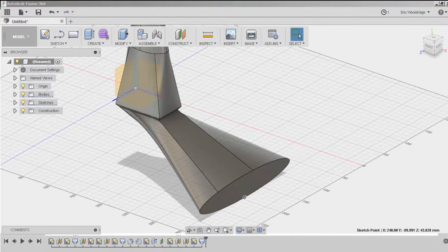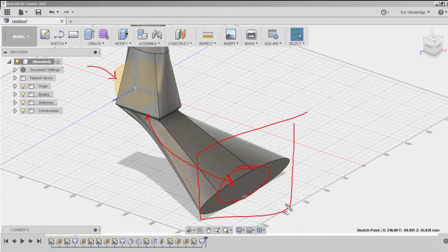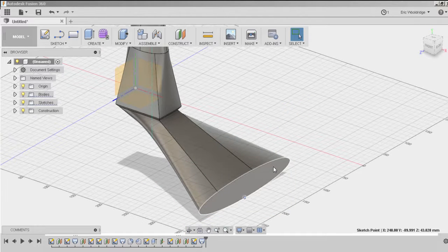So just to go over our steps once again, you have to create an offset plane. So we created it out here, a certain distance away. Then we drew an ellipse, and then we did the loft command and selected this one first and translated it to that. And then we went back into our sketch features and just changed our shapes and played with it. So don't forget, you can always come down and right click on your sketch that you created and say edit sketch, and then change things around. All right, go ahead and pause the video and do that now.